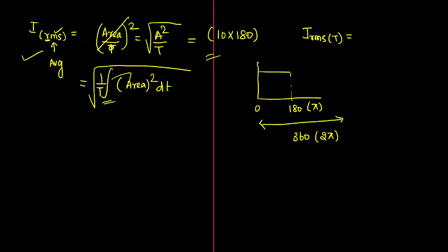So this is 180 degree, I can keep it as pi. Substituting gives the direct formula. Otherwise you can solve here also. Magnitude is 10. For the RMS value, I know directly the area is given. Instead of area, we put the integral. I should keep all of them under root. But the area you have to square. That is very important, because root mean square value.